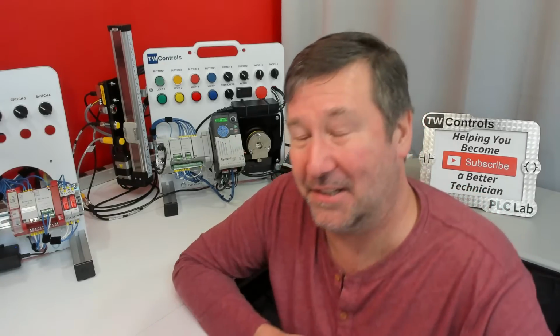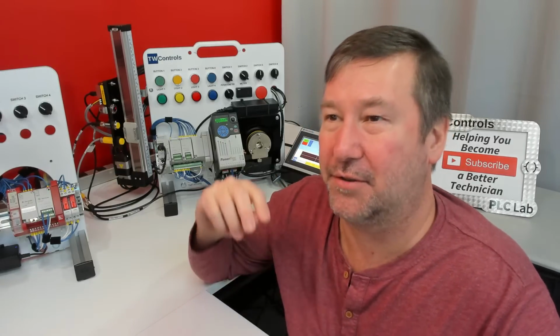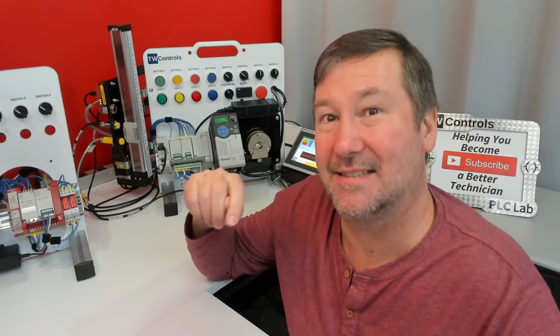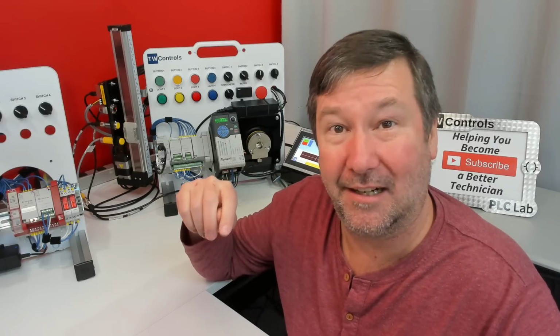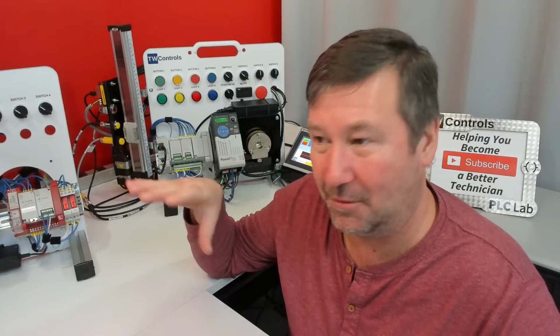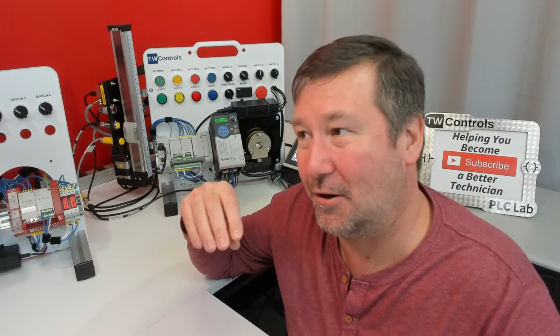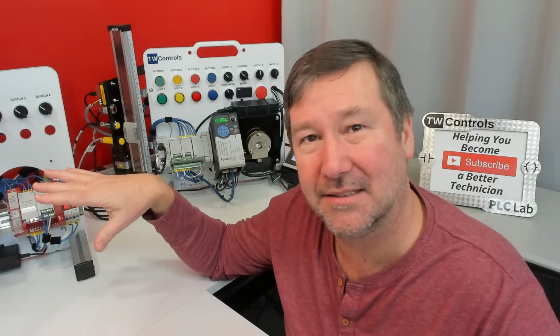Now, I know what a lot of you are going to say right away, and you'll probably put it in the comments if it's not live. A lot of people say, well, there's a warning in Studio for that. There is. But first of all, duplicate destructive bits are not necessarily wrong. I see lots of programs that have them, and the way they're used, they're perfectly fine. The other thing is in a larger program, you're going to have like 300 warnings. It's normal. Nobody is going to look at those and see the duplicate destructive bit warning.